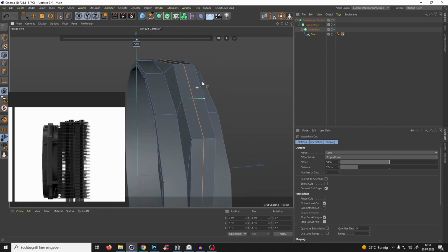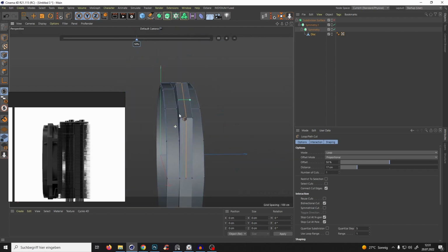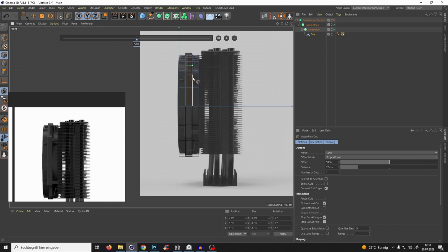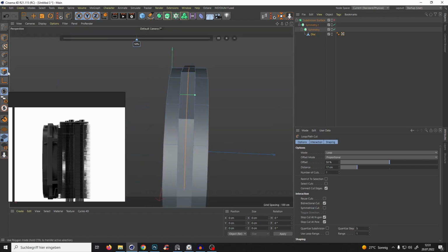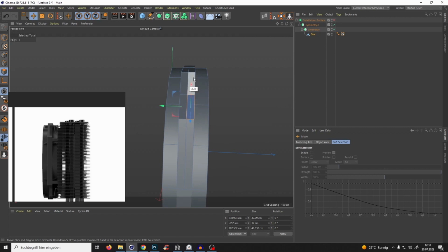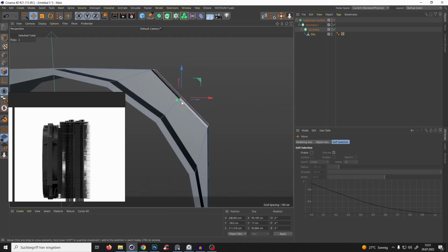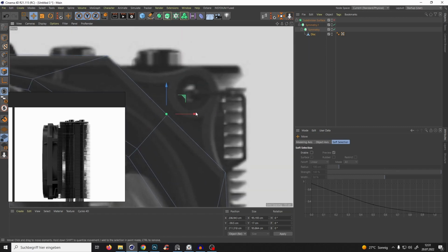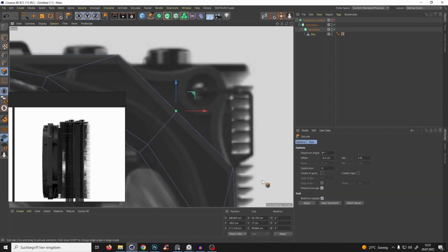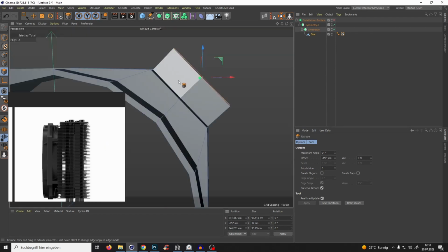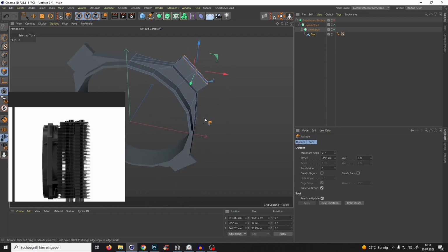So we have something like that. And now remember, this is our right side, so I'm looking at it from the right side. We can select those two edges this time. And we go to the front view, and again with D for extrude without caps, bring it out a little bit. Something like that. Okay guys, that's it. I hope you liked it.